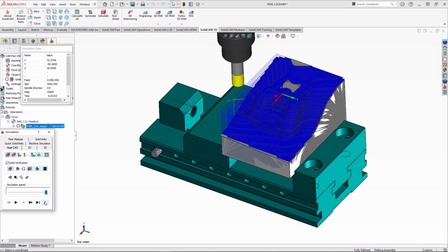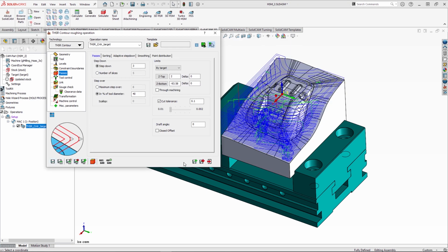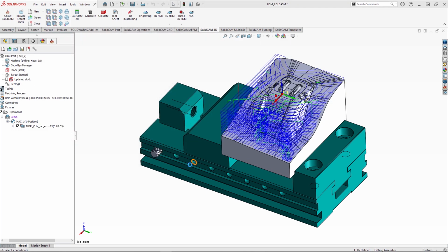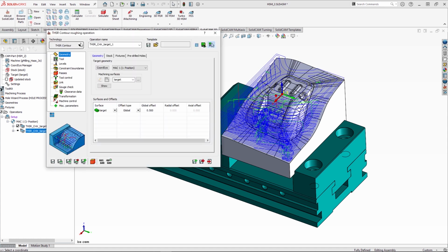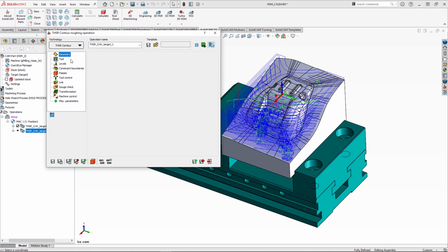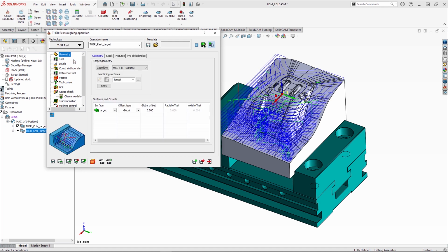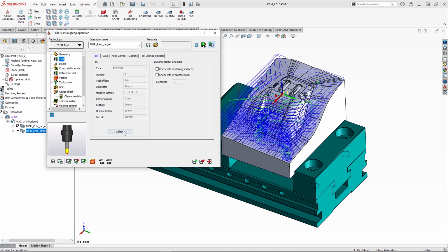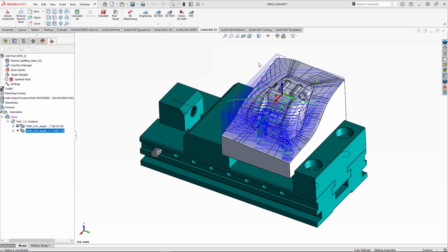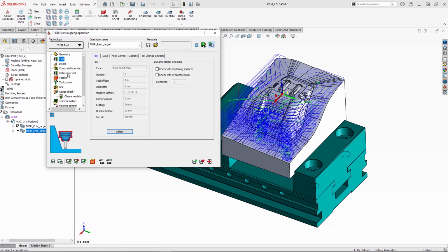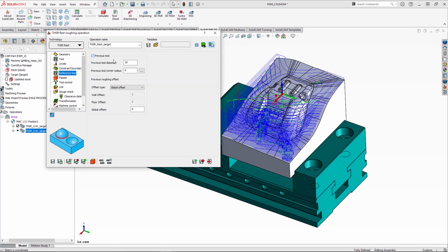require. And from there we might have some areas that might be too deep for us to come in with a finishing pass, and therefore we could use rest roughing. Turbo HSR is really easy to turn into rest roughing. Just by the drop down you can click THSR rest. From there all we need to do is change the tool, and in this case we'll use my 8mm ball nose mill. And then we can also pick the reference tool, which I'll just assign a diameter of 20mm, and it'll use the global offset for roughing.